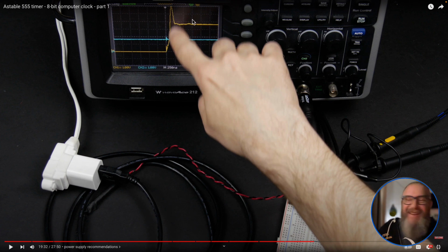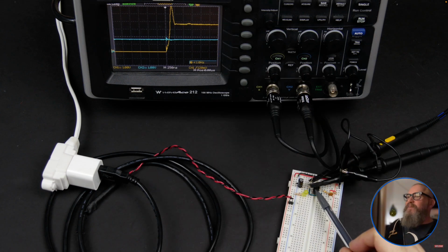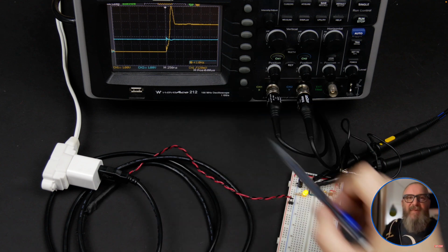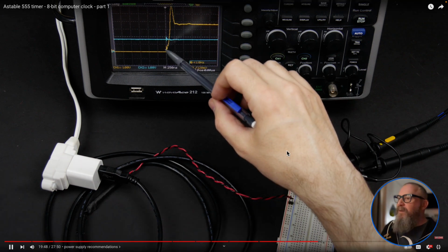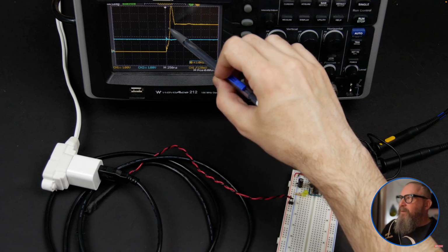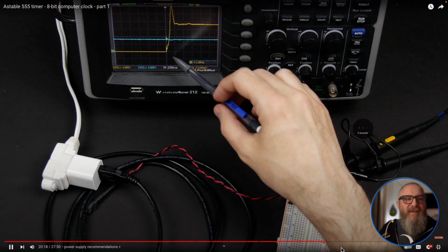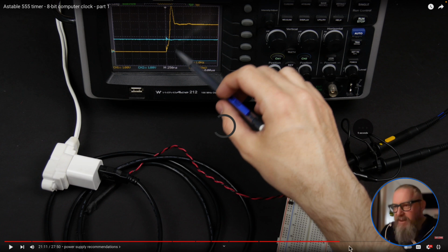The hobbyists and people who just want to go to the edge will ask, what happens if we push it here? Can we go here? Does this particular chip, one that doesn't have the manufacturing defect, let us push it up to here? Nope, that's too far. There's some overshooting here, and what's happening is when the output wants to turn on, there's a bunch of transistors in here switching, and when they switch, there's a different current requirement. So they want to pull more current from the power supply, and they're not able to pull that current as quickly as they would like to, and then they end up getting more current than they wanted, and it overshoots. Yeah, so he goes into details of what can happen when you're overclocking stuff.